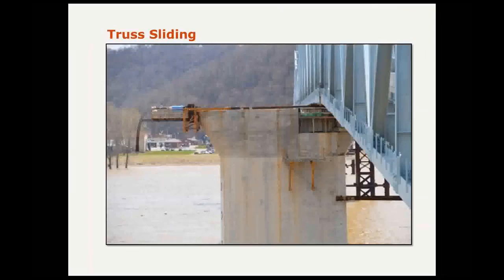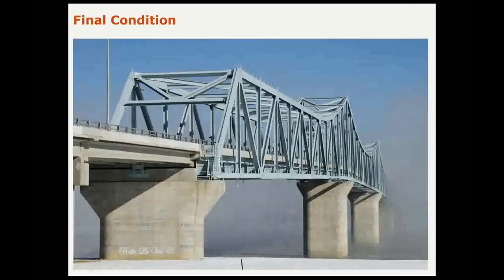So now the cap is poured and the slide's underway. You can see the cap is still unfinished on the right side, and it has to stay this way until the bridge is in its permanent position, in which case we can put the final closure pours in place. And here's a shot that shows the piers in their finished condition and the sliding girder pockets filled in.